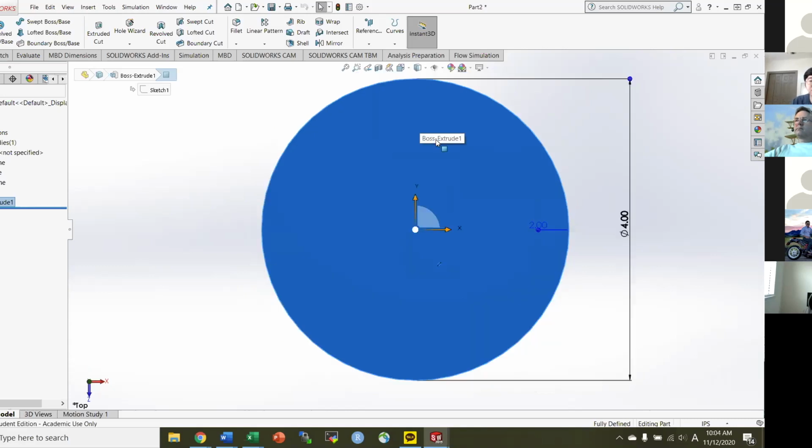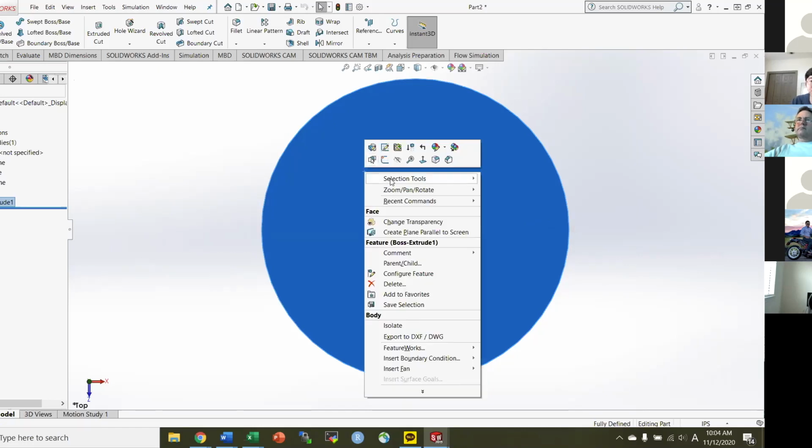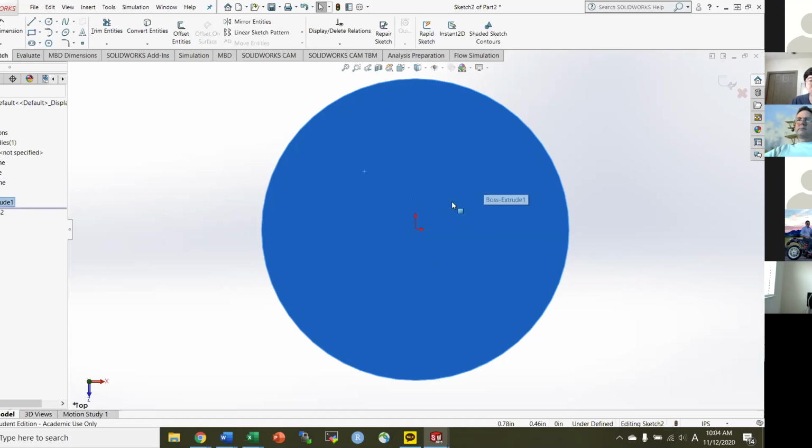So if I click on top and then go to top view, I can right click on the surface and it'll show different options. Right now I want to click on Sketch. There's an Edit Sketch also if you want to edit, but right now I'm going to make a new sketch on this. And like it happened for the top plane before, it'll now designate this surface as my plane where I can sketch. And if I sketch another circle, point at the origin, and draw it out.